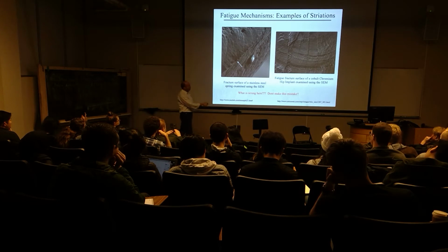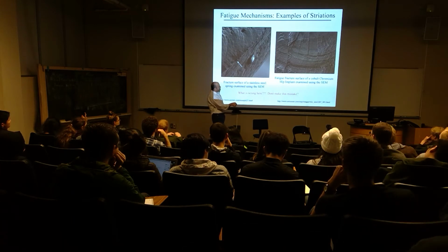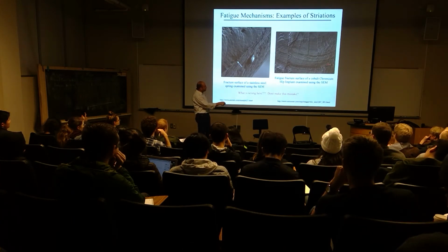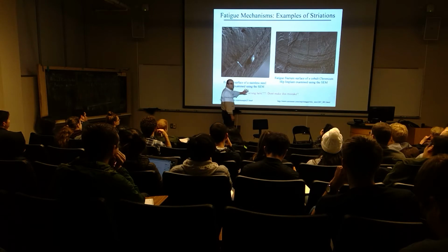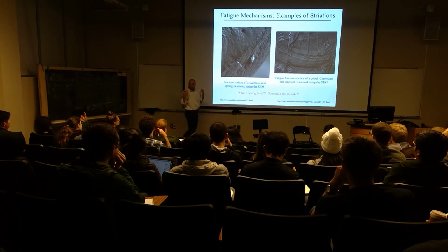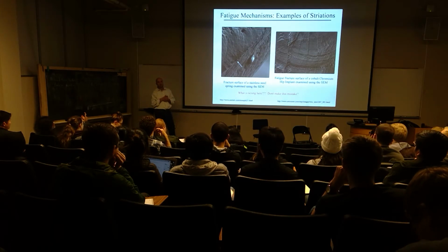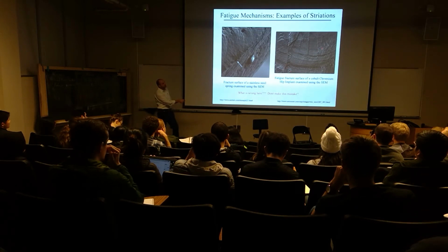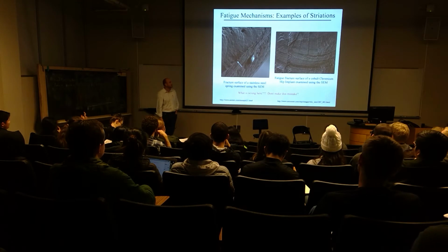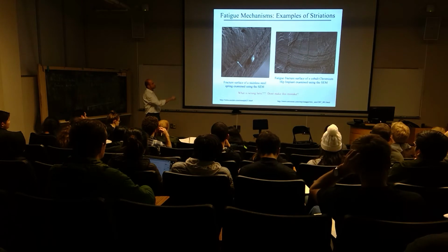And then what you'll see here on the right is actually a mixture on this chromium fracture surface of a hip implant. It's examined by SEM, but there's a beach mark that's right there, and there's probably another beach mark, but the rest of this stuff is actually striations. And I apologize, there's a big problem with these. The problem is you don't have the scale markers to show you what the scale is to indicate, hey, I know that's really a striation, because that looks like a bunch of beach marks at that level of magnification. But you also see something there that's pretty important to you. Those are ratchet marks that are extending from the origin point. So those are the beach mark locations, and then these other things are the striation positions.